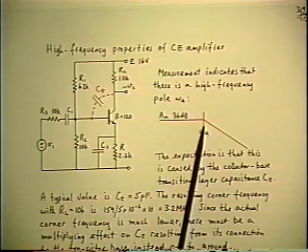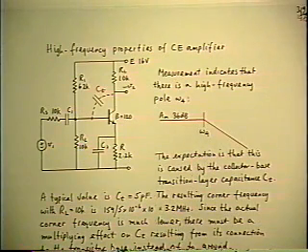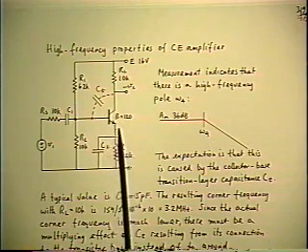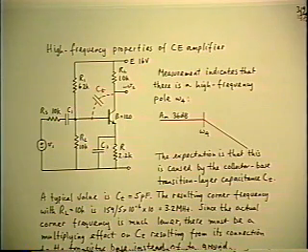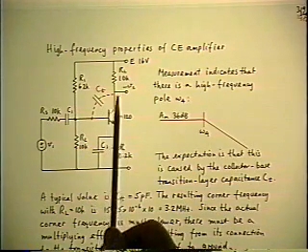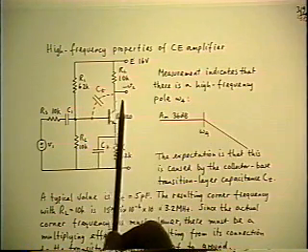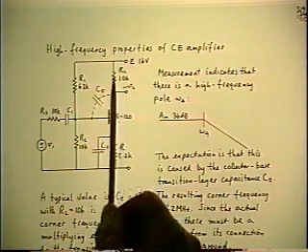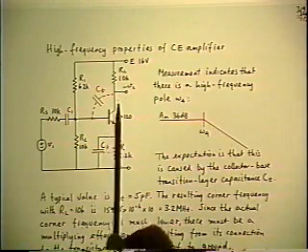Obviously, that is not the explanation for a 47 kilohertz corner. The discrepancy is much too large. So rather than dropping the idea and looking for some other cause, suppose you think a little more carefully about whether the CT really is behaving like that. Because the 3.2 megahertz is the corner that you would get if the CT were directly in parallel with the RL. But it isn't.